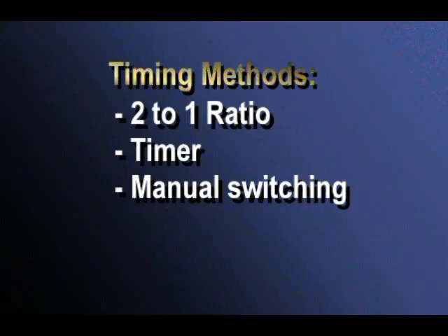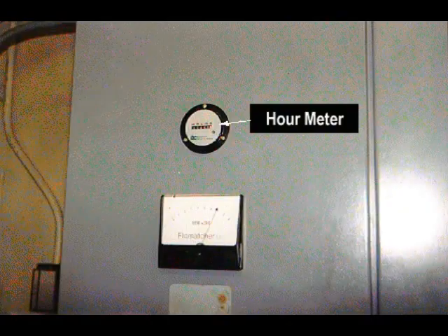An hour meter and pulse or start counter on each pump could provide an accurate check on the amount of use each pump is receiving. In this picture, note the hour meter used to keep track of pump usage.